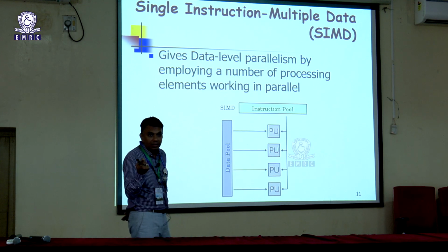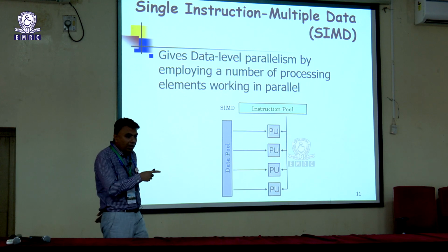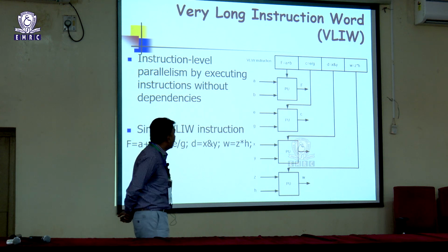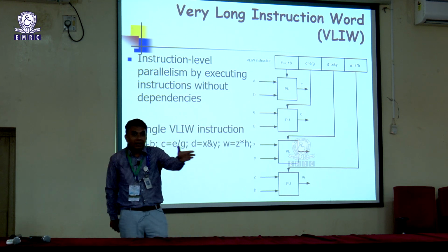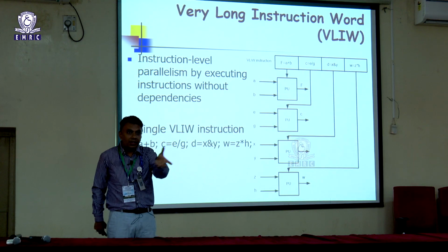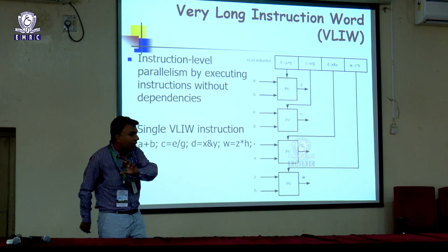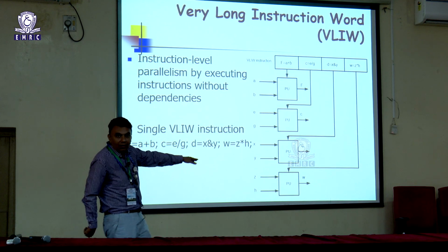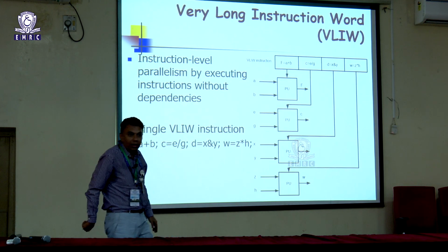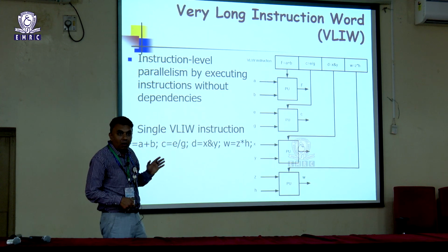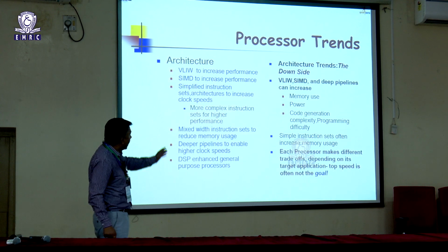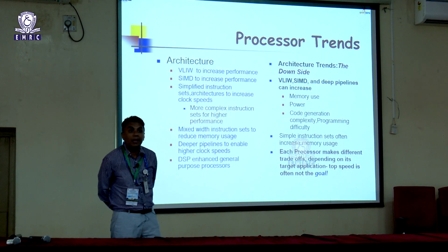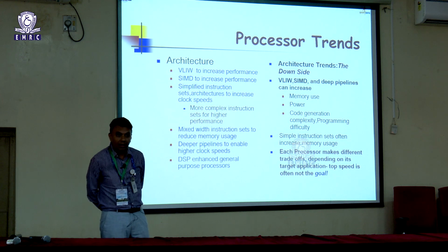So that is called single instruction multiple data, meaning a single instruction will do n number of operations in a single cycle itself. The second thing is the very long instruction word, where you do instruction level parallelism, meaning a single instruction having a lot of small instructions. Like in a single instruction, one addition, one division, one multiplication and so on. So in a single instruction you can do multiple operations together. These are the two things on which all advanced DSP processors are built. So architecture wise, they have both VLIW and SIMD architecture, although deep pipelining is also nowadays happening in the DSP processor.